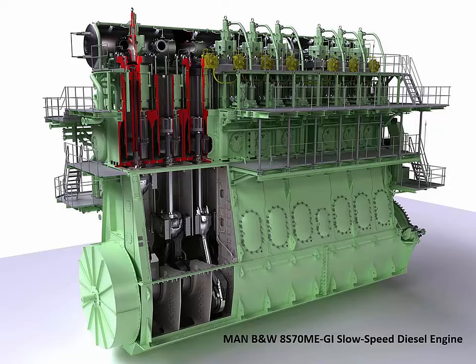Well, let's say you're doing 15, 18 knots out in the middle of the ocean. When you shut the fuel off that engine, that vessel has way on. That water is moving along the hull, striking the propeller blades and turning this main engine over. It's going to revolve at a fairly high speed. So to try to stop it, you would have to expend enough air to counter that turning force, stop the propeller, and then turn it into the astern direction. Above 8 knots, you probably will not be able to do that.